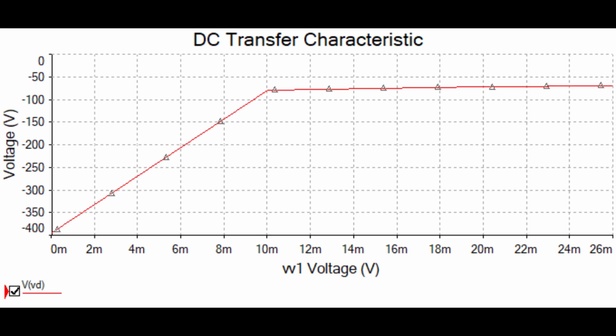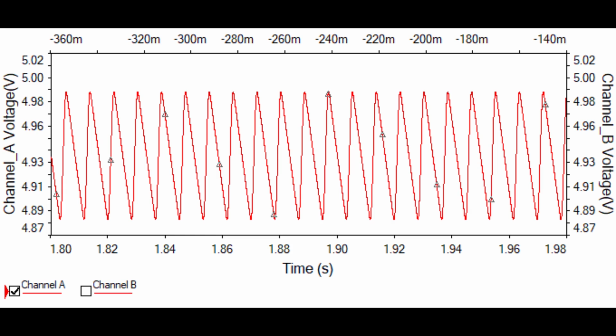One reason for the slight discrepancy is that the diode drop for the maximum input voltage is slightly greater than 1.0 volt, rather than the assumed 0.7. The ripple voltage is approximately 0.1 volt, which is within the 0.15 volt specification.